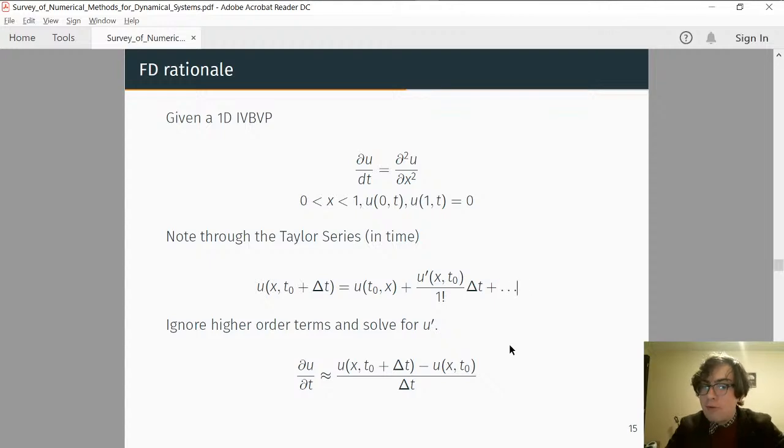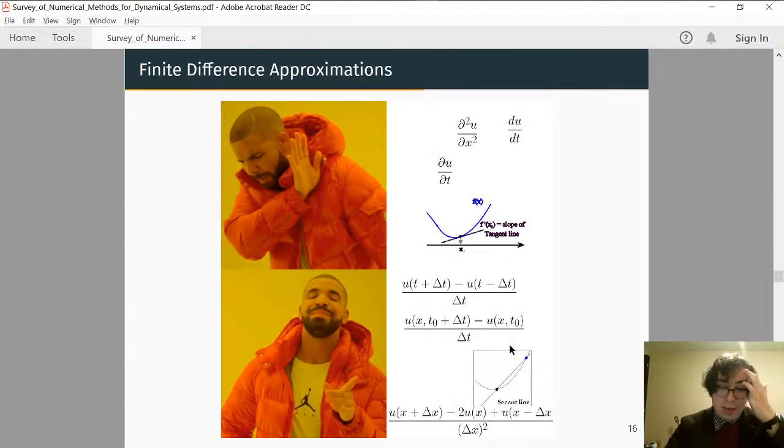And when we cover these topics in depth, we'll look at what's called stability criteria, which says if you choose a time step any larger than some set value, not only will your solution be inaccurate, it will be infinitely inaccurate. It will blow up. When I say it blows up, I mean the error goes to infinity, which is no good, right? When someone asks you what the error is that you solved this with, and you say, oh, the error is infinitely high, they're probably not going to trust your solution that much.